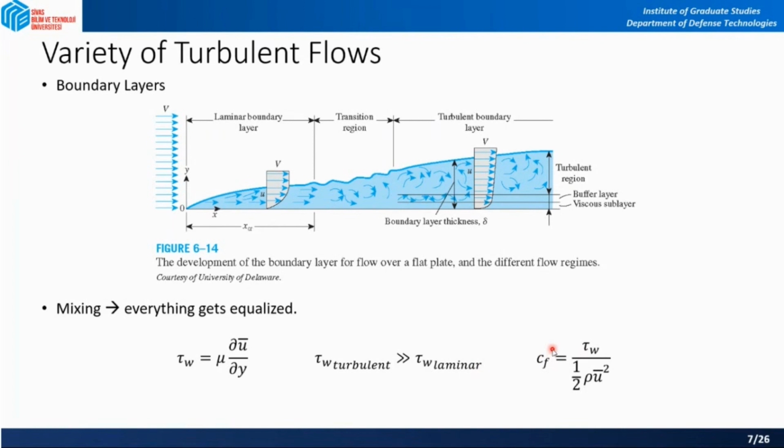But in pipes, in internal flow, no such thing happens. In pipes, once the flow is turbulent, it remains turbulent. External flows are a little different, but the arguments that we have are more or less the same. So did you understand why the profile shape is different?